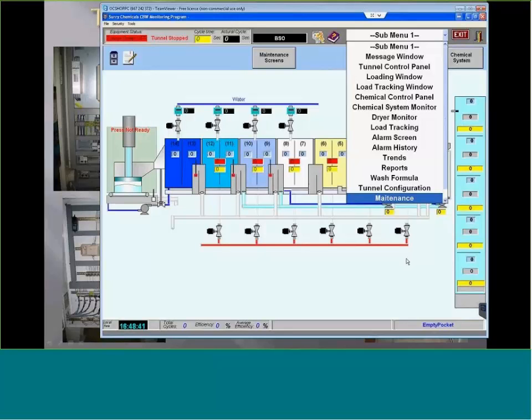Myself, I use three areas of errors. I use an events type messaging, not necessarily errors, but holds, like temperature holds that are just waiting for temperature or water levels to be met. Those are not any kind of acknowledgement errors or faults. Then I have what I call a non-critical error.